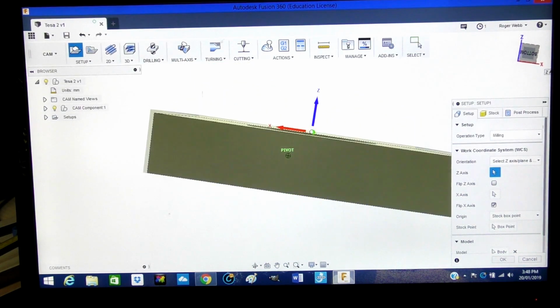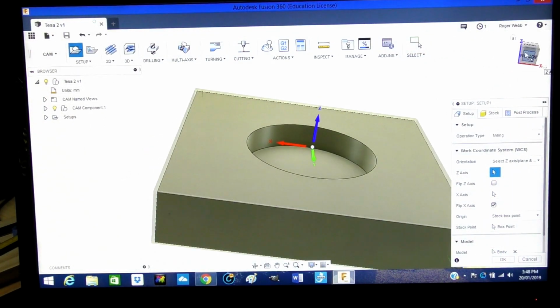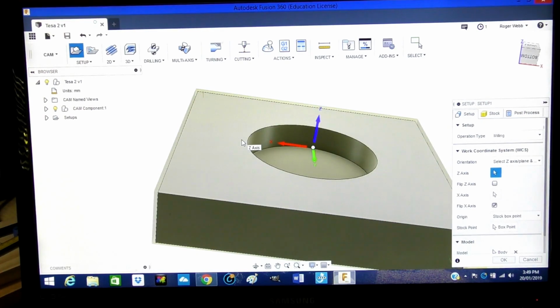That's all around the top and the sides of our material. Now, what Fusion 360 has done is created excess stock material. Well, we need to turn that off because in this situation we don't need that. If you're starting with Fusion 360, you really don't need this extra material.